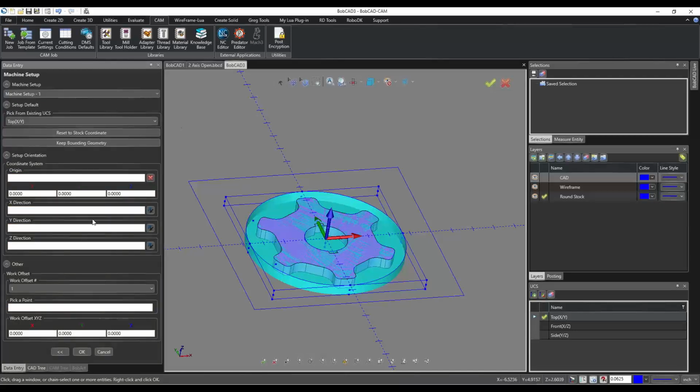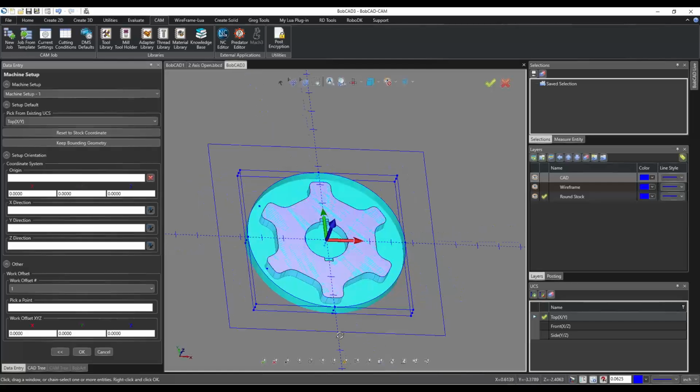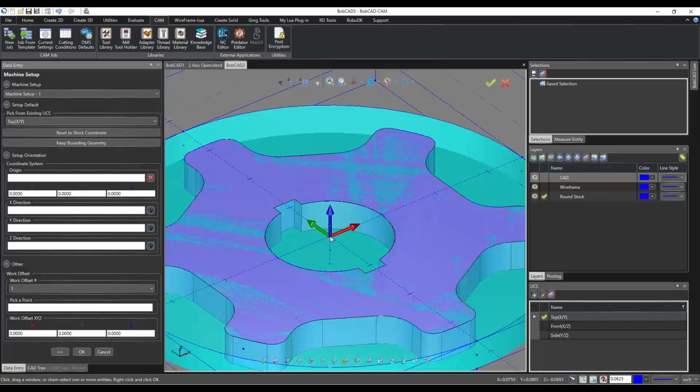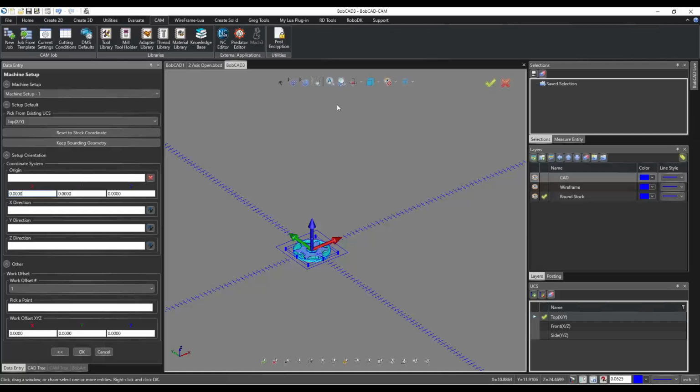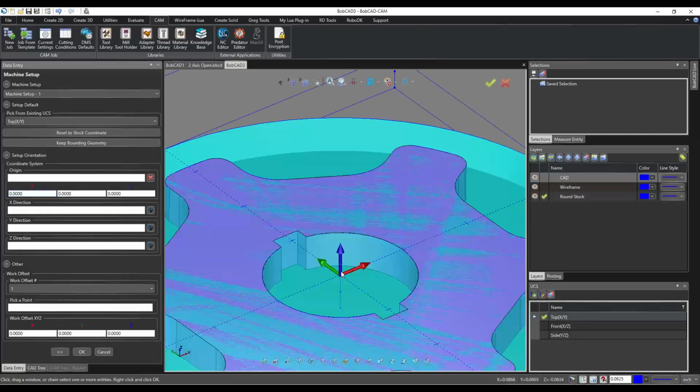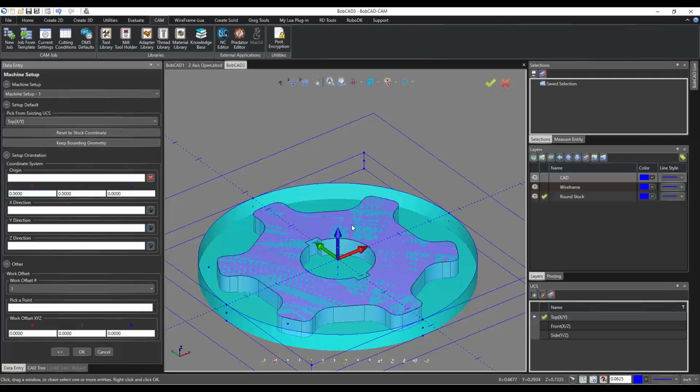And now this is the page where you set up that machine origin location. So I'll just leave it set to the default here, which is just the center middle. Basically, the default is just 0, 0, 0 of the CAD origin. So depending on where this is placed in the CAD space here, the default is always just 0, 0, 0. So if you ever need to move it though, you use this page here.